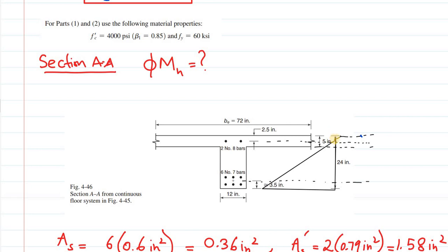This is a very shallow distance of 0.92 inch, c value, depth of neutral axis, and this is the level of compression reinforcement, 2.5 inches, halfway between the mid depth of the flange or the slab. We have compression reinforcement, so-called compression reinforcement, because this is actually acting as a tensile reinforcement. It is lying below the neutral axis, and even this is yielding, 0.005. Even this is yielding, and definitely the tensile reinforcement at the level of centroidal tension reinforcement has to be yielding, especially this dt value. These are much larger strains.